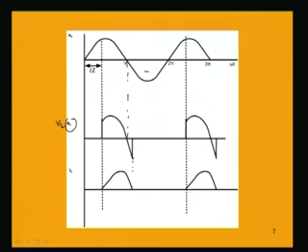After this becoming 0, it will continue to be 0 again till alpha is crossed. So, again the current will start to flow, and it will continue beyond 0 value of the input voltage, and after some time only the current will become 0.